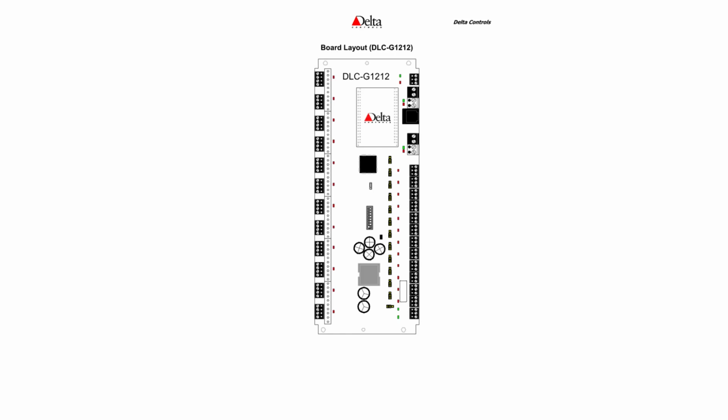So on this, like I said, the left hand side is where you connect the relays, but on the left hand side there's also another set of wires on the newer relays called RR9. There are 2 yellow wires, and those 2 yellow wires will give an indication into your DDC system for a log of saying a relay is working or a relay is not working. So you connect those 2. But on most of the buildings, you don't have those extra wires. You just start to use those relays if you have a digital control such as this. So this will be the low voltage lighting controller.